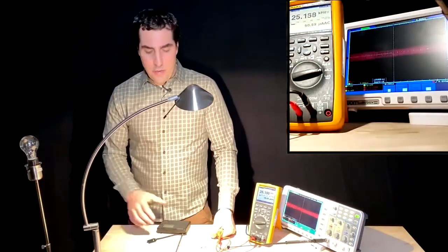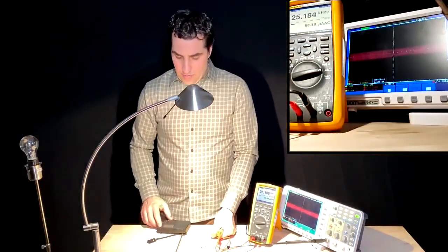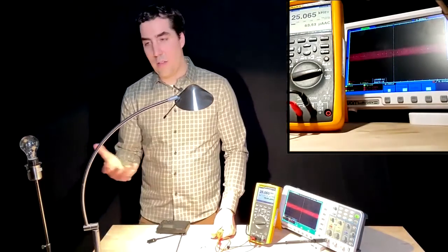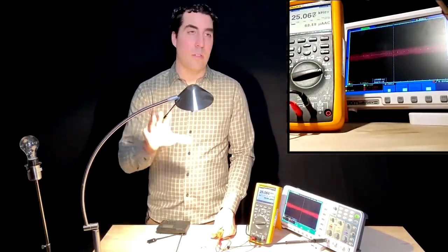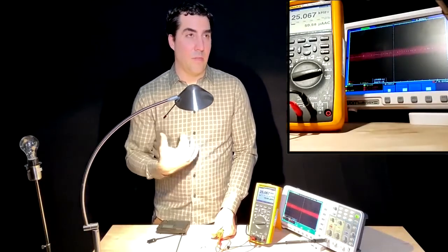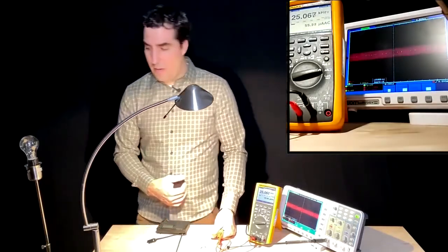And as soon as I do that, I'm just going to turn off the AM radio here because we know that it's, right? We see the oscilloscope go up. We see that we're now at 25 kilohertz, 25,000 hertz, instead of 60 hertz, which runs in our electrical system. We're now at a much higher frequency. So there's quite a bit of electrical noise at 25 kilohertz. When that frequency increases, there's more current that can pass through me, measuring myself using a body current method.